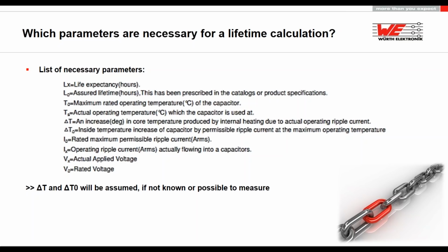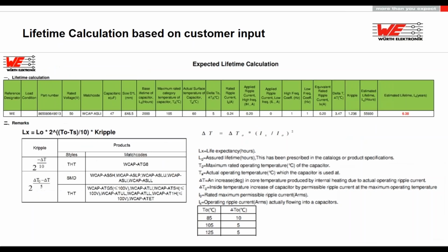So sure, life expectancy is a result of this, but what we need is the applied voltage, the rated voltage of the capacitors, the ambient condition, the temperature, the frequency of the ripple itself, and then we can do assumptions. And just a quick example of what we can do for a client: if we have this, then we can run an expected lifetime calculation.